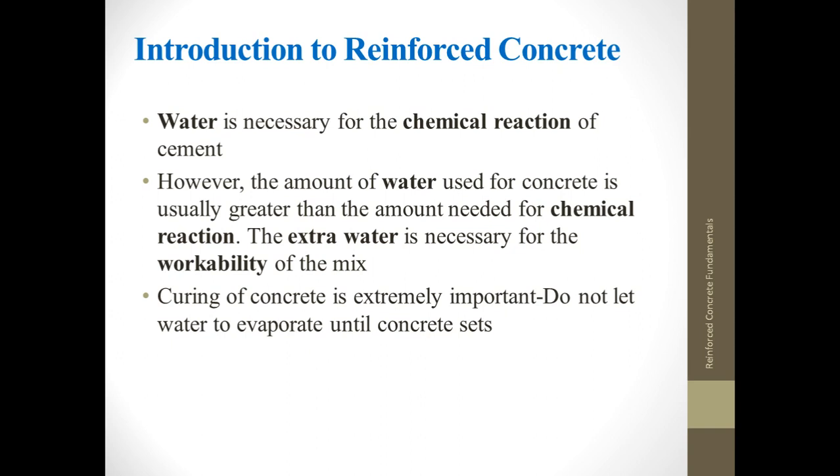A concrete is said to be workable if it is easily transported, placed, compacted, and finished without any segregation. To measure the workability, there is a test called the slump test. The concrete slump test measures the consistency of fresh concrete before it sets. It is performed to check the workability of freshly made concrete, and therefore the ease with which the concrete flows.